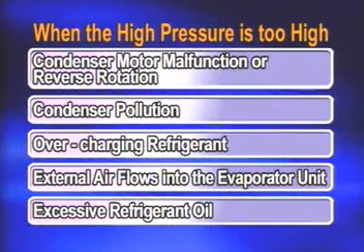When high pressure is too high, check the following: condenser motor malfunction or reverse rotation, condenser pollution, overcharging refrigerant, external air flows in to the evaporator unit, excessive refrigerant oil.